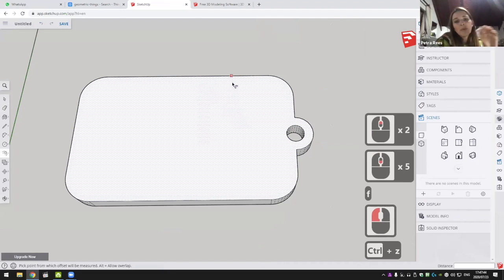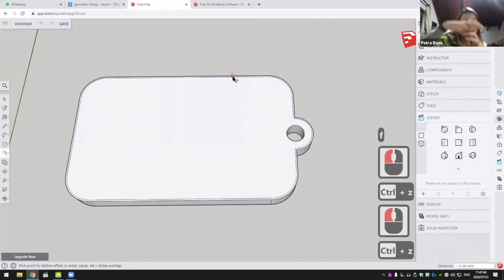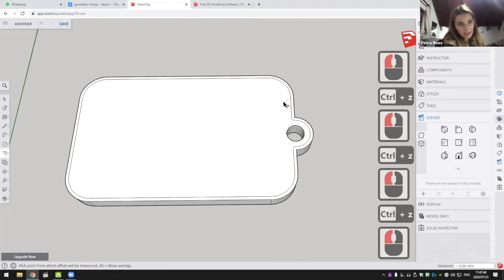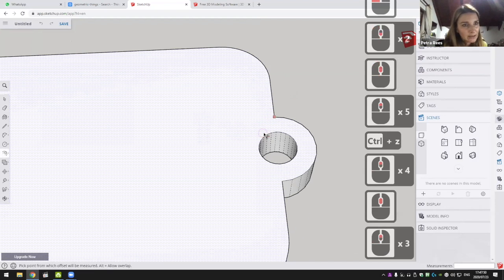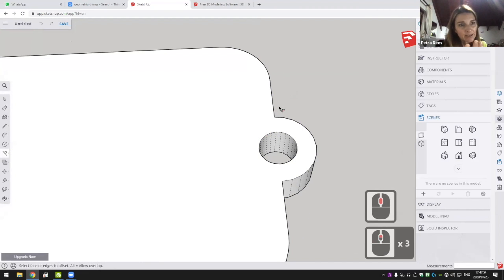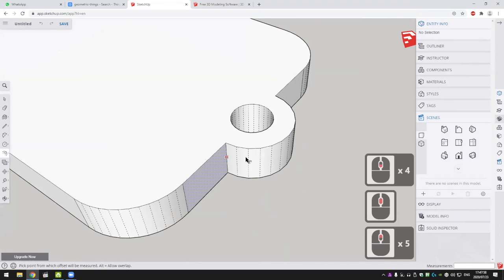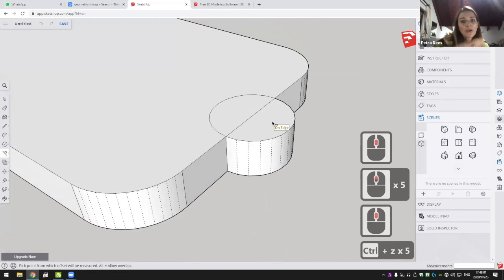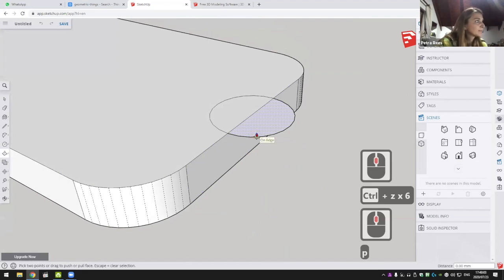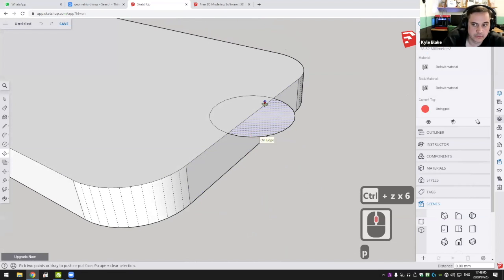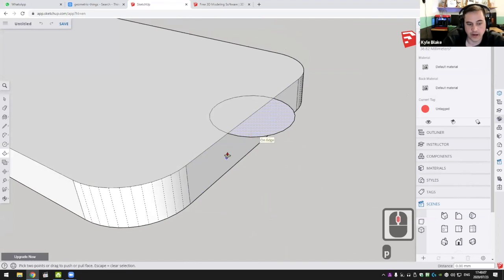And then when you're making the circle, when you're building it up with the height of the rectangle, I forgot what the height of that rectangle was. And when I'm putting it down, it obviously goes all the way down. I don't know how far I should go down. So what you can do, so you're at this point, right? If you've forgotten how tall your rectangle is, there are two ways. You can measure it. If you press T, it will bring you to the tape measure.